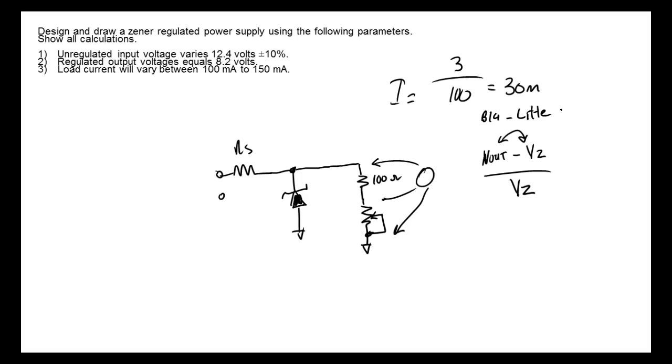Does that make sense? So this is the circuit that we'll hook up. And why are we using a 100 ohm resistor? Well, we're using the 100 ohm resistor so if you come up here and accidentally turn that pot all the way to 0, you don't have a short, right? You understand that? And then plus there's another feature, that we can use that as a shunt, right? We can measure the voltage across it and use that to calculate current without doing what? Without breaking the current and using an ammeter.